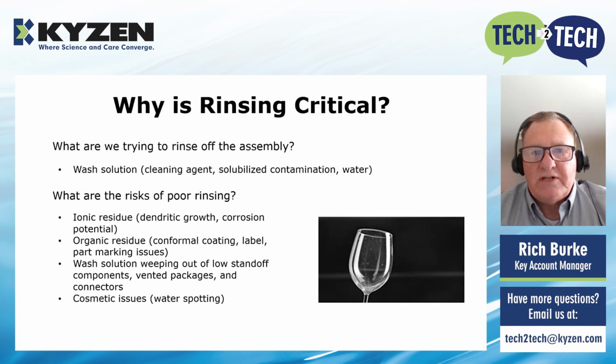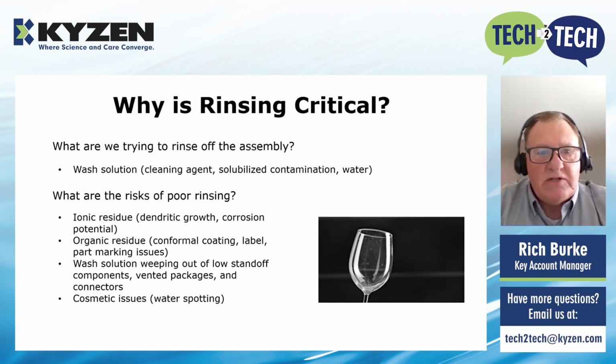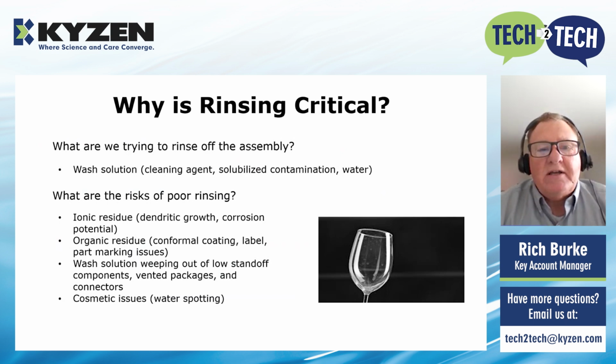If we do not rinse those off, what are the risks? What may happen? Well, it depends on what the residue is. In the case of an ionic residue, we can see dendritic growth or corrosion potential. If the residue left behind is organic, that can be problematic when it comes to bonding. That could be bonding of a conformal coating material, bonding of labels, or part marking issues that may arise.